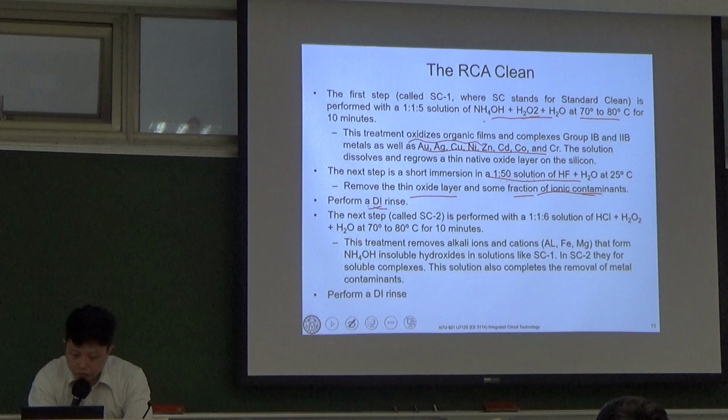And then the next step we call it SC2. It's performed in the HCl and peroxide solution, also at high temperature for 10 minutes.